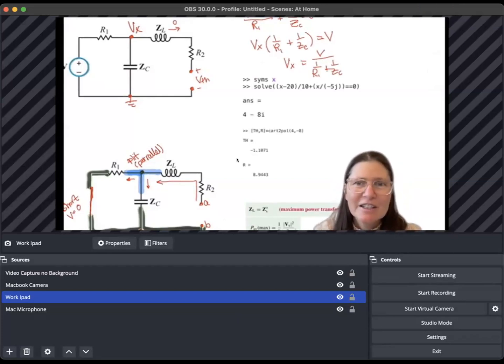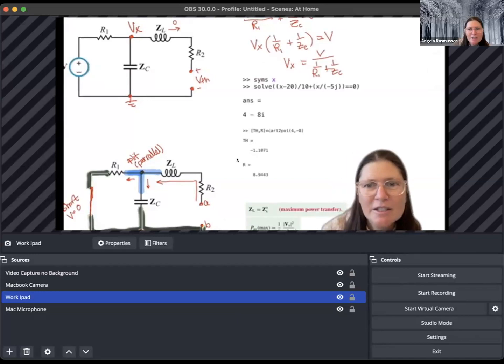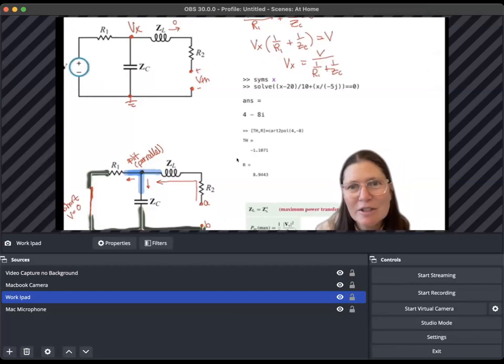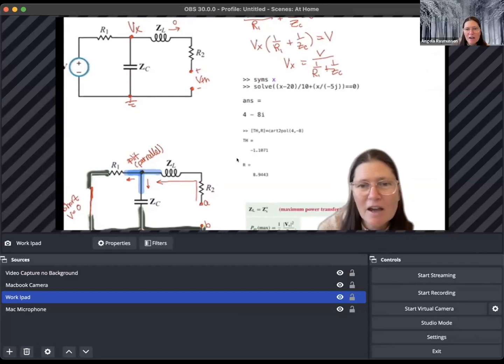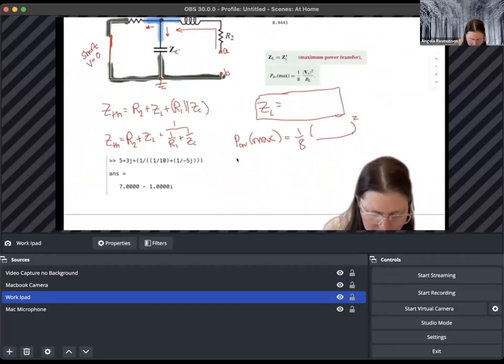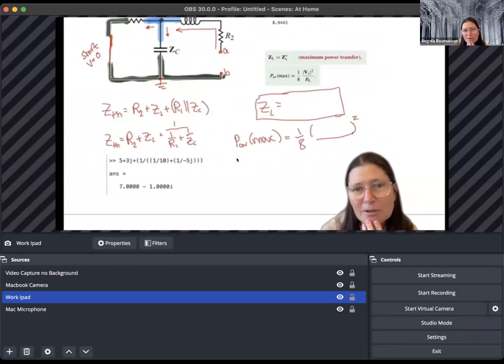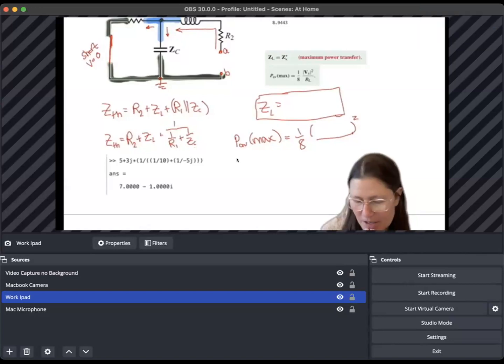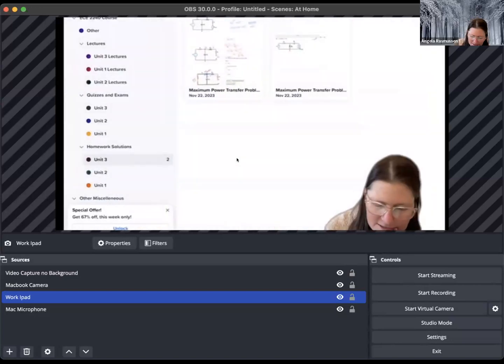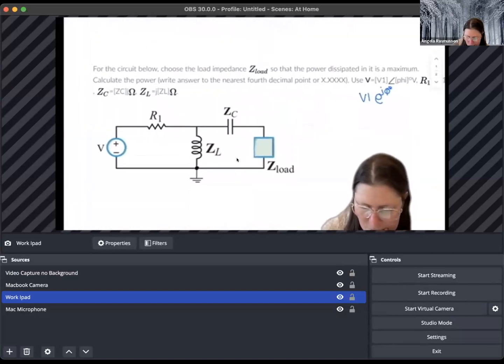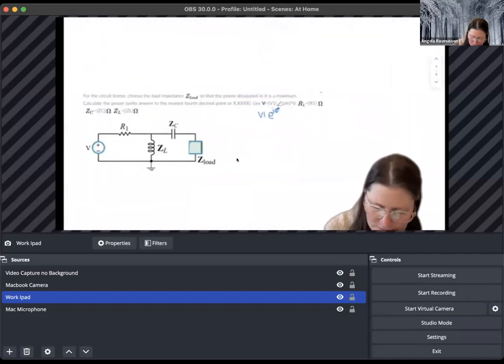So chances are in a circuit analysis question, not for maximum power, we wouldn't see a voltage and then an angle to it. The angle's not going to change the magnitude of it. And it's not going to have any effect on the ZTH portion because you're only looking at the elements themselves.